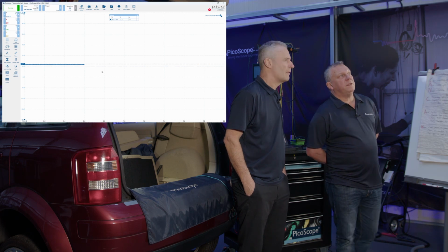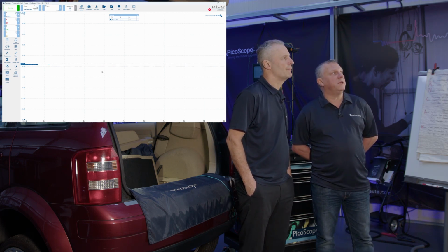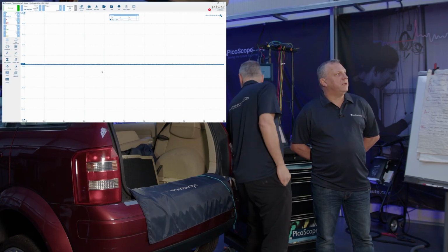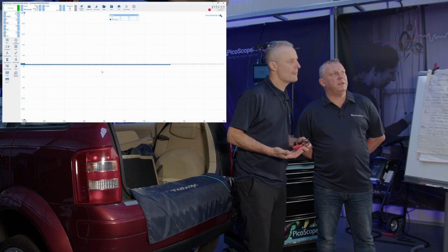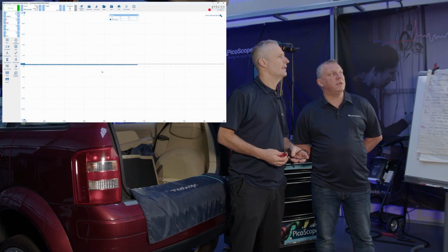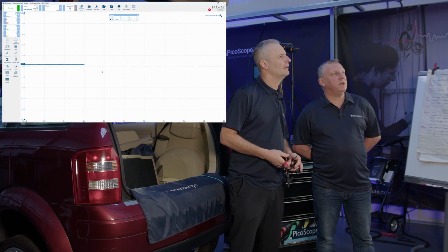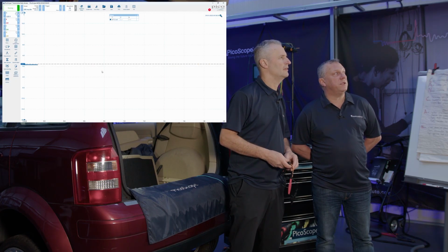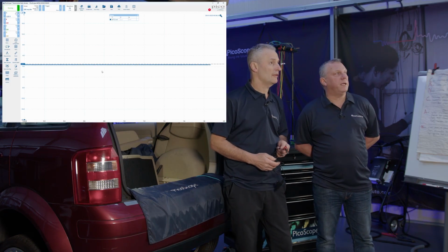It's a good point, Steve, and obviously if you don't stop and think about it, you'd never consider what that is, and you would just assume, and we all know what assume means, that it is 0 volts. But obviously the leads are still connected to the vehicle. Although they're not connected to the battery, the components within the vehicle contain capacitors, which are now storing electricity, which is slowly dissipating. But how could we speed up the process and get it down to 0 volts?